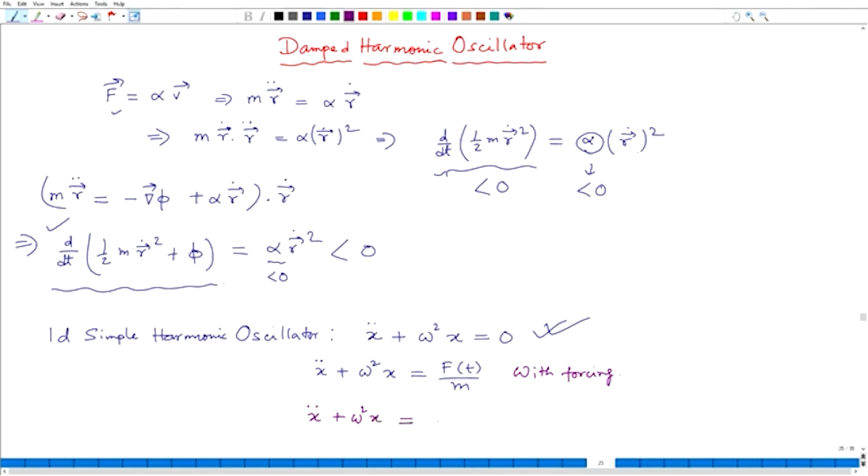I am now just considering no forcing which can pump energy, but some dissipative effect. So, I can write with some minus 2 lambda x dot. Okay. This is a forcing whose coefficient, lambda, I am just considering to be greater than 0 here, and this minus is just to ensure the dissipation of energy, and x dot is the velocity. So, that I can write.